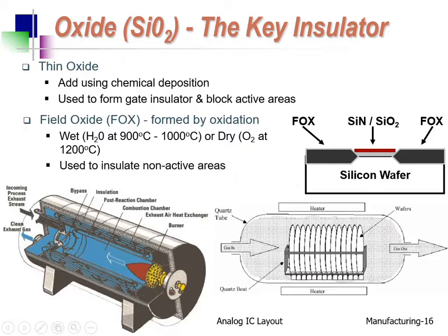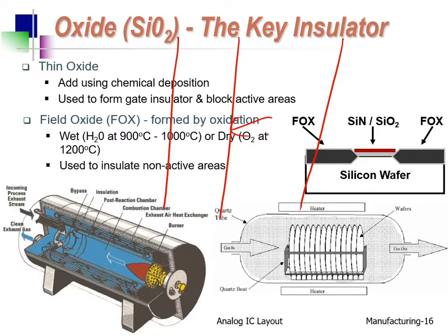Among the wafers, you can see, the wafer looks like this. How about the middle? How to do such oxidation? Where to get oxygen for oxidation? Oxygen needs to diffuse from the boundary to the middle, right? So what can you guess? The oxygen density is higher at the boundary and lower in the middle, right?